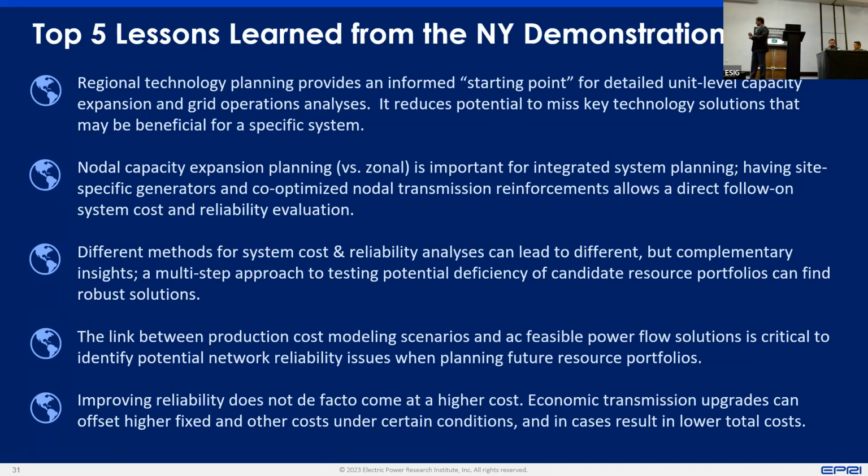Then the second takeaway is linking your zonal model with your nodal model, and that's what we did by linking ReGen with PLEXOS LT, which was nodal. That gives a very good starting point for further analysis into production costing and transmission. So linking your zonal analysis with nodal, that was the second takeaway.